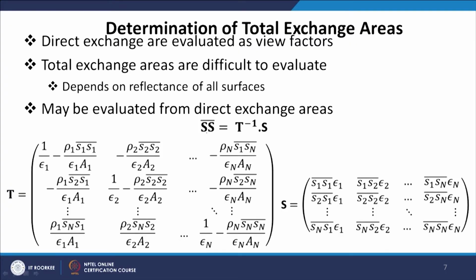Now, how to evaluate these total exchange areas? Direct exchange areas are evaluated as view factors. There is no difference, because direct exchange areas are directly related to the view factors. However, the calculation of total exchange area is not straightforward, because it depends on reflections from other surfaces. So, total exchange areas cannot be calculated in any easy manner. But we can make use of energy balance, and we can derive equations to find total exchange areas in terms of direct exchange areas.